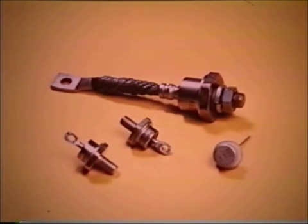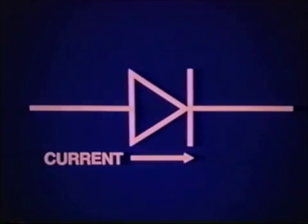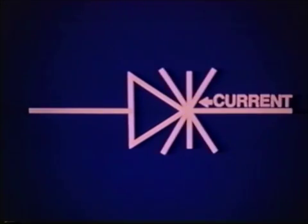Today, modern rectifiers are solid-state diodes and are usually constructed of germanium or silicon. This illustrates the electrical symbol for a diode. Notice the current flow direction in relation to the arrowhead. Current attempting to enter the other direction is blocked. Only current in one direction is allowed to go through. A rectifier is actually an electrical check valve. The rectifier will allow flow in one direction, but will block flow in the opposite direction.